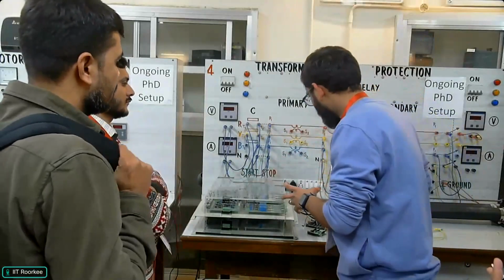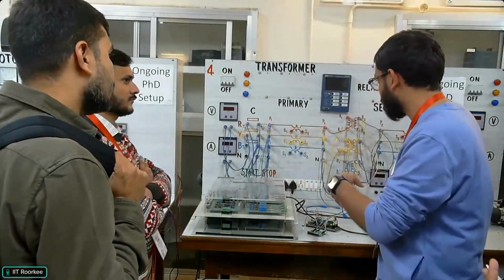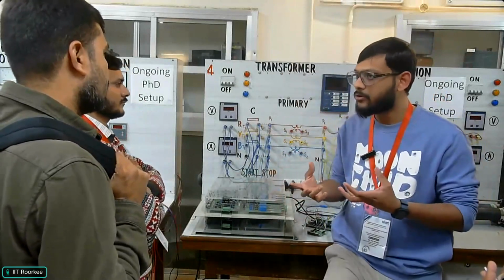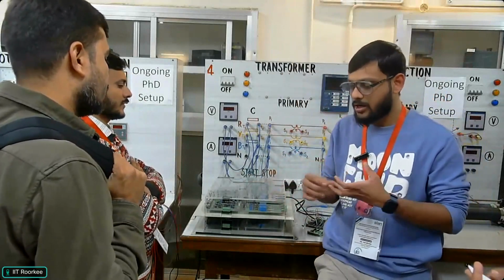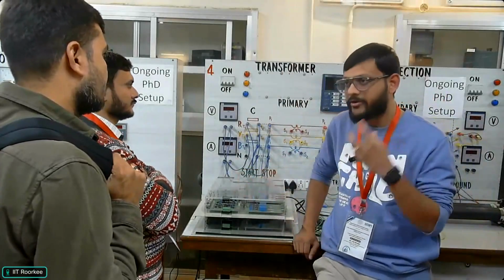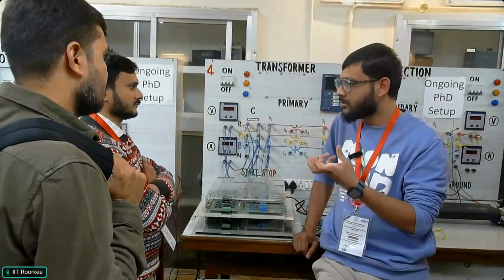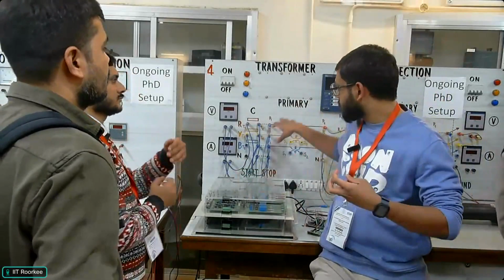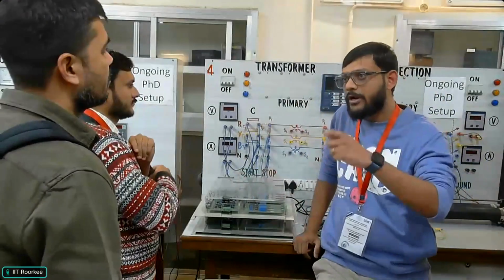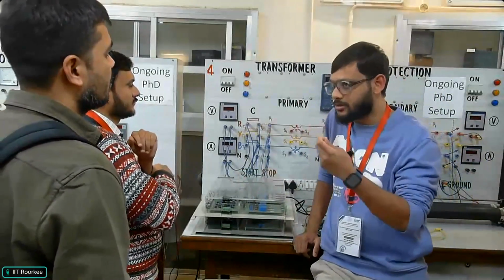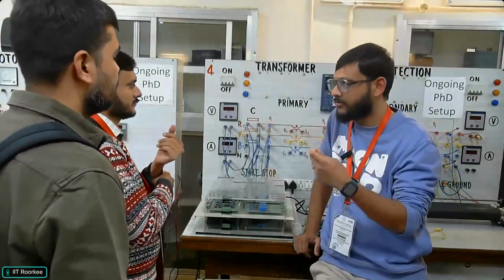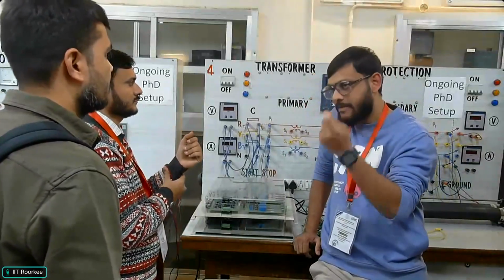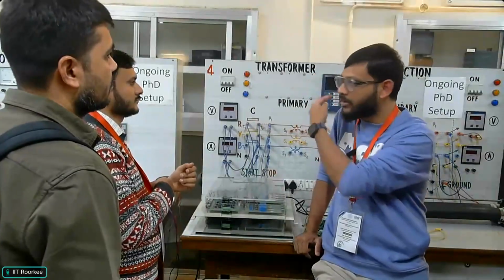Now, to get these things, what automation can we do? Currently, automated substations are replaced by merging units. These merging units will sense the currents at the field level only, and convert them to digital signals or sample value packets. You will see how the packets and everything work tomorrow. These sample value packets will be directly connected to the relay.